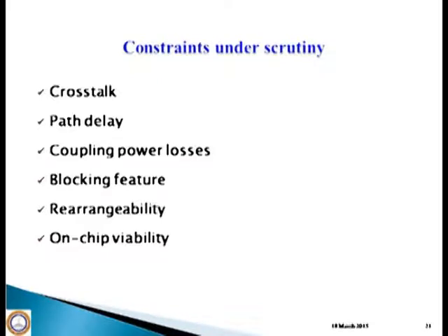Coupling power losses: when we couple power from one port to another port, or to many other ports, there will be coupling losses, so we need to tackle those losses also. Blocking features: if we can have all combinations of input-output connecting patterns, then the switch is non-blocking. So we need to take care of this also.